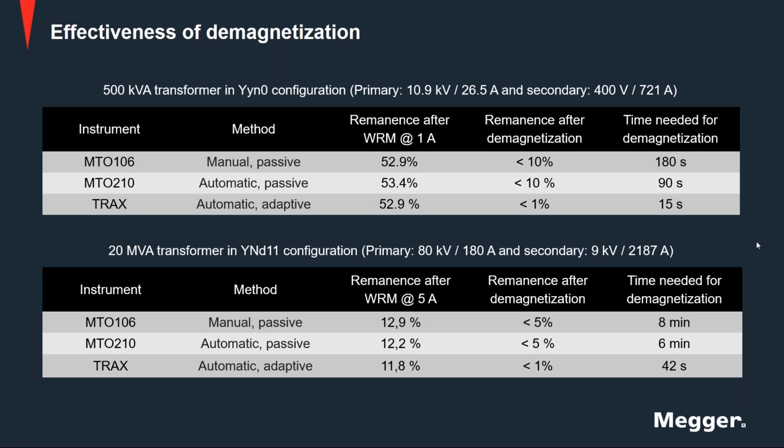I have tested a large transformer that had been tested previously one year before. In that testing, we found that the transformer was fully magnetized. Our excitation current had actually gone more than 2 times the expected.